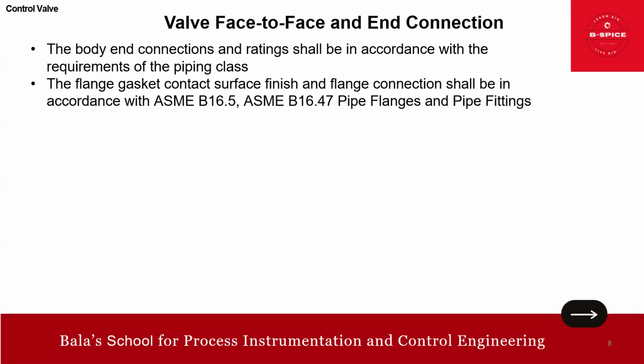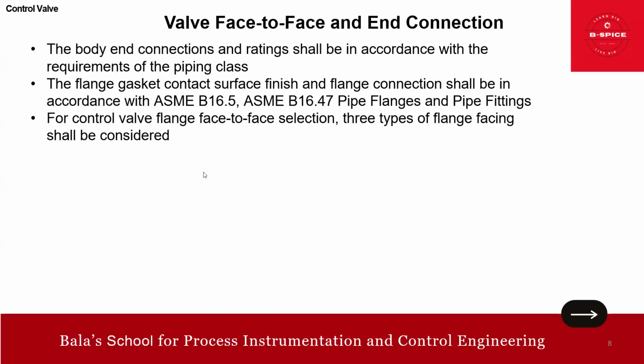Okay, friends? So the point is the flange gasket contact surface finish and flange connection. I will tell you what that surface finish is, okay? And flange connection shall be in accordance with ASME B16.5 and ASME B16.47 in some cases.